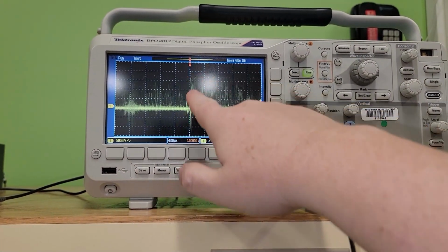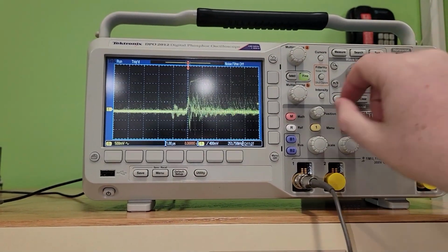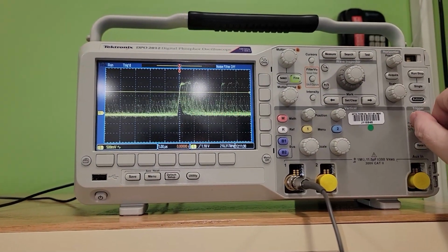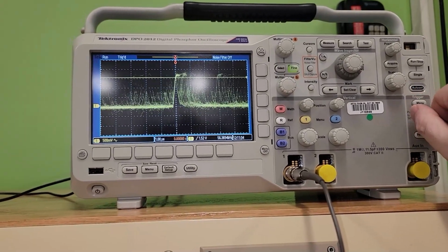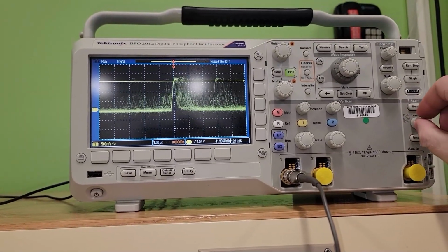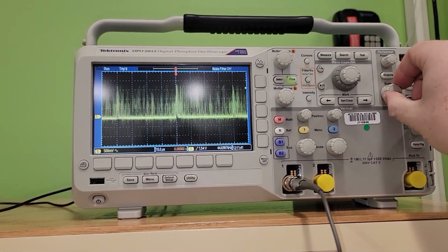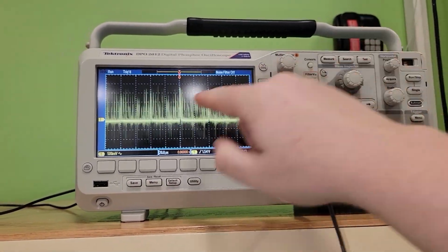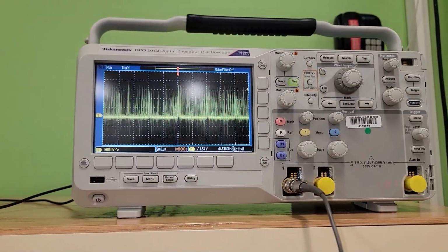This first signal, I want you to take note of it. This is part of our sync, horizontal vertical sync. As a matter of fact, if I bring this up, barring where I trigger, we can make that a bit clearer. This is all the red information. This is analog red signal. We can see that that strongest peak repeats itself with the signal coming through. All right, so that's our red.